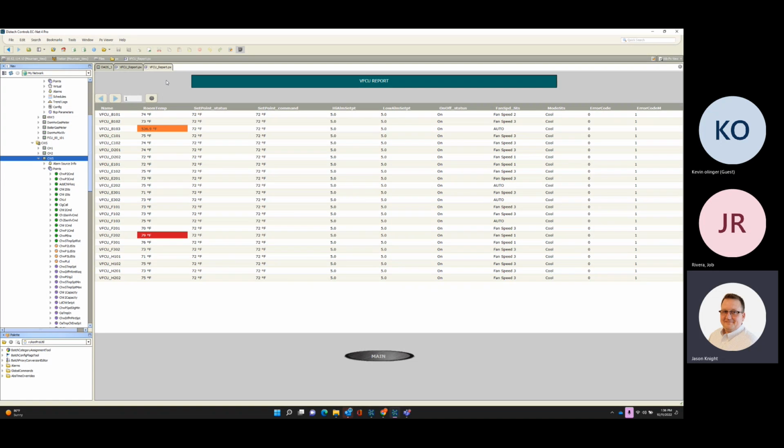But we still got to get some things figured out with the loop pressures and what they're going to do with that whole thing, because the pumping sequence might completely change again. So I don't even want to go down that road yet. Sure. We know that to keep the building stable, we have to maintain 20 pounds. And on paper, the minimum differential to be able to push water at the right GPM and maintain the discharge air temp between 55 to 58 degrees, on paper, it says we have to do a minimum of 6 pounds.